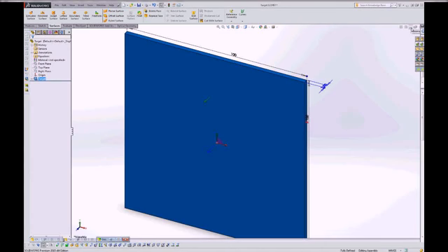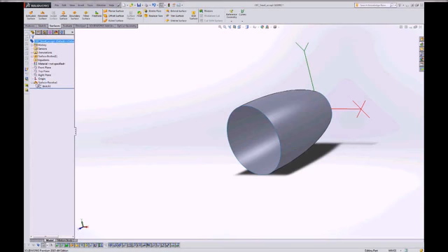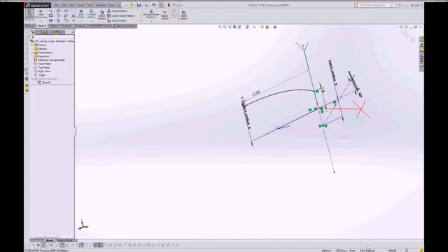And what I'd want to do is to combine those. One thing I didn't mention here on my CPC: notice if I come back over here, Feature Manager, and edit my sketch. One thing I do want you to remember is that when you're designing components that you're going to be using with ray tracing, you need to make sure that you fully define your systems to make sure that things don't accidentally change in size or position. So before I created my CPC model, I did indeed have a fully defined sketch.